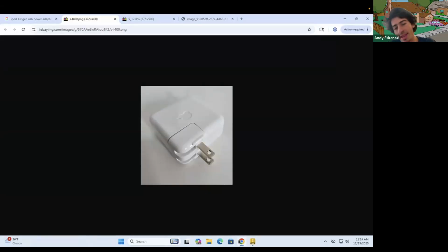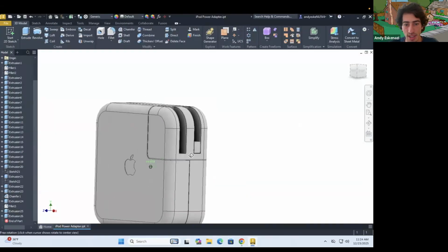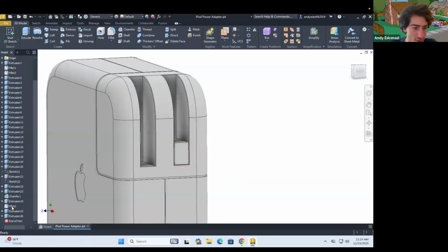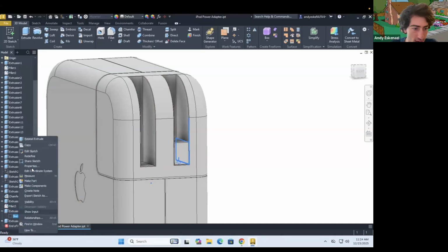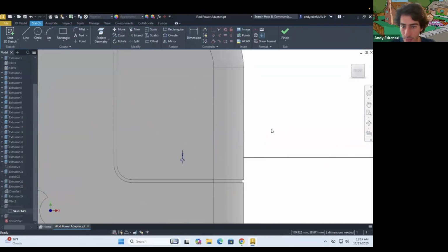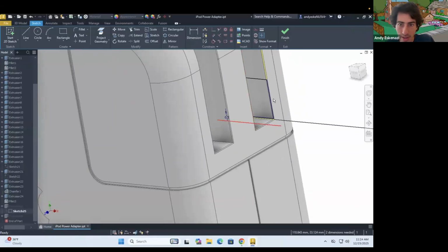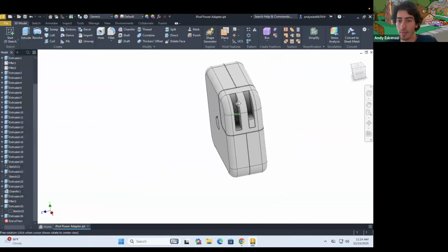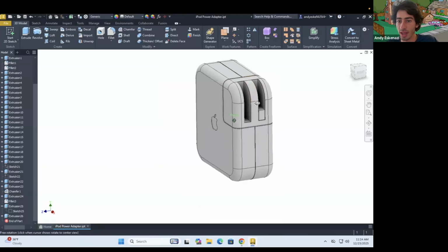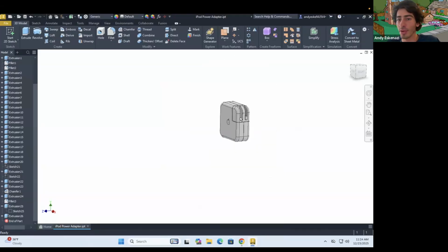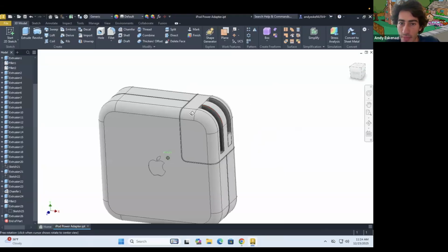Okay. And then making the pins that will extend from this will be a walk in the park. But at least that's actually the height of that looks kind of nice, even though I don't think I really fully defined what it was gonna be. Edit sketch. I didn't give it height. So maybe I can do that explicitly right now. I'll make that 30, as a matter of fact. There we go. We can pretend that, yeah, like that, just that will collapse again into itself.